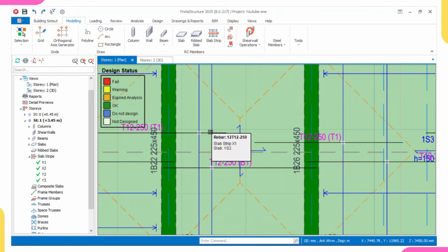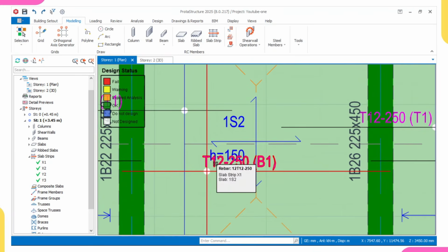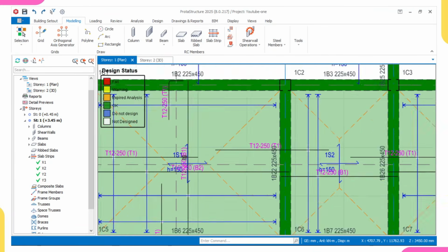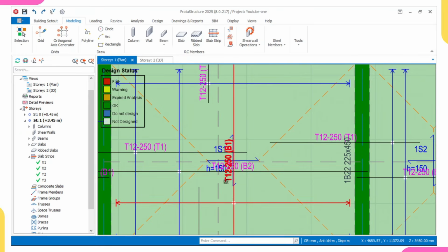The steel yield strength we assume to be 460 might be 410. Even the Y12 might no longer be Y12, it might be Y10. So in my design, to counter all these things, I'll use Y12 at 200 spacing, even though the design gave me 250 spacing. In all my slabs, the spacing will be at least 200.